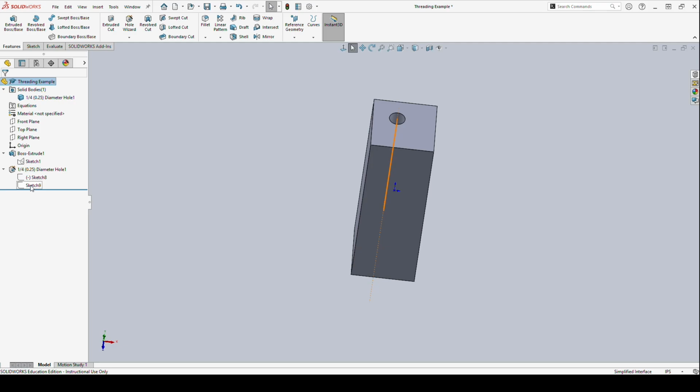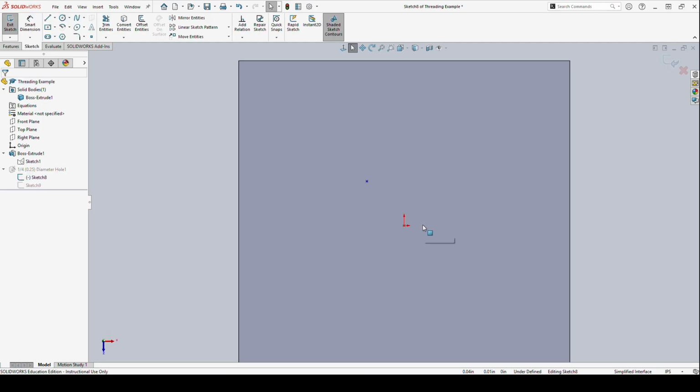Ideally, we have everything within our SolidWorks model defined. And this sketch is our position. So remember, we just kind of selected somewhere in order to say where our hole was, or our holes were if we had multiple of them. And that point was just where I clicked on a face. We want to have this locked down somehow.